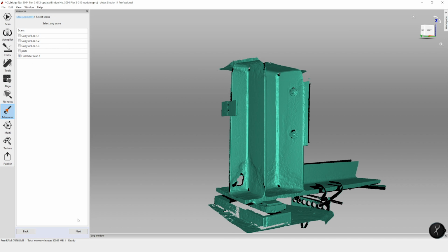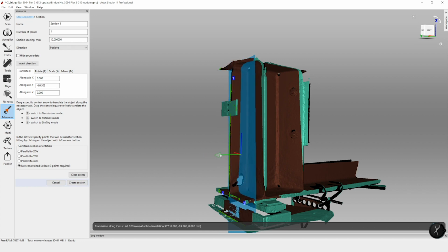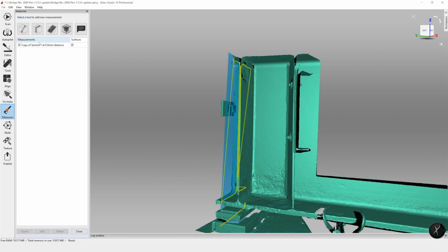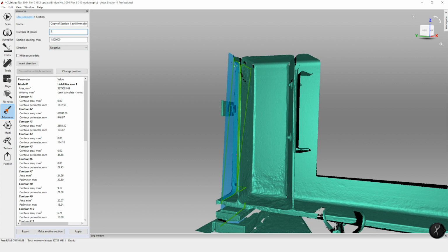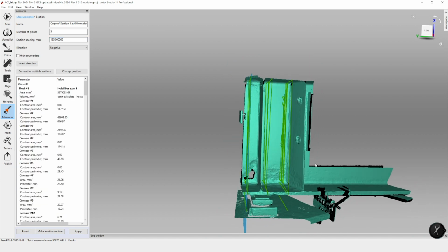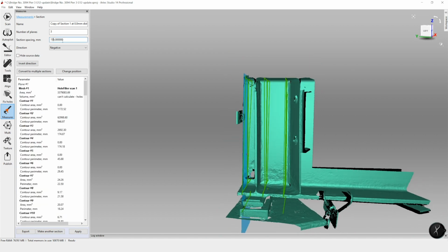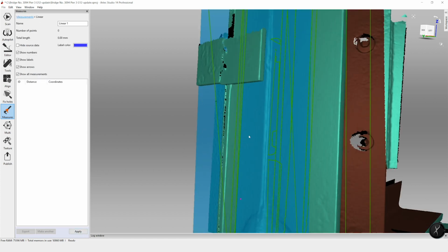So we start with the section cut and then do our individual linear measurements, the same way that was done in the past videos. We're going to start by making that first initial plane and then copying this plane along the length, so we have those multiple reference measurements that we can pick our points on. This makes it very helpful. Of course, if you're doing an initial check, you can just go in and select points. You can skip this sections tool, but I find it helpful as a guide.